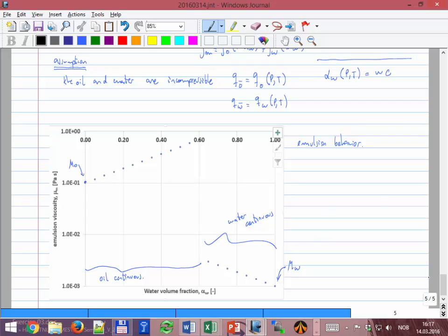Okay, so here is plotting on log scale. Don't wonder why it doesn't look exactly like what we discussed before, because the model that we are using is exponential, so in a log plot it shows just a straight line. And you see that it goes almost 1 order of magnitude, close to, I think, 860 or something like that, centipoise. So it can increase quite dramatically when water is dispersed in the oil. This is oil, we are plotting it green, and the water is just some droplets.